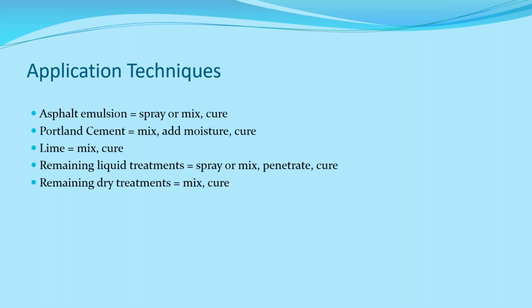Okay. The next question is, can you elaborate on the treatment that you mentioned at the start that did not work for the road on the cover of the Unpaved Road Dust Management Handbook? Yes, it was actually a company out of South Africa that was trying to market a sulfonated oil. When you're dealing with some of these companies, they'll tell you that their product is proprietary, but we ended up getting a sample of it and testing it.